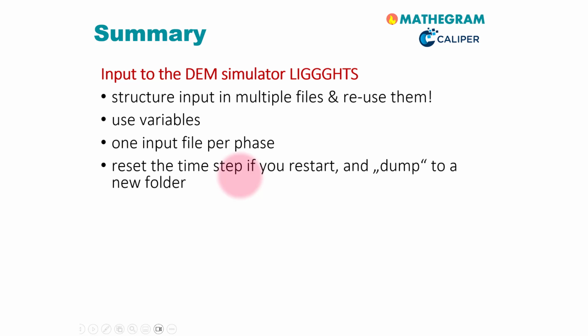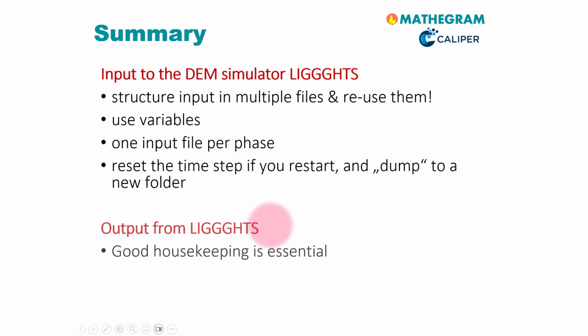This is important for good housekeeping reasons. The output from LIGGGHTS can be split up into multiple files. This again is important for good housekeeping. Especially if you run a large number of simulations, it's important also to have a smart naming of your folder structure.